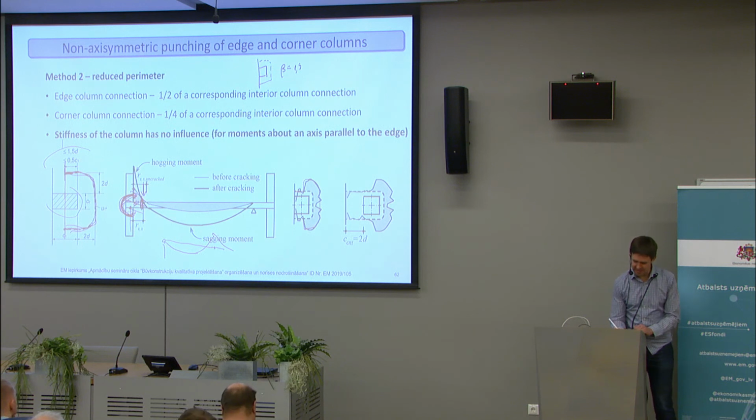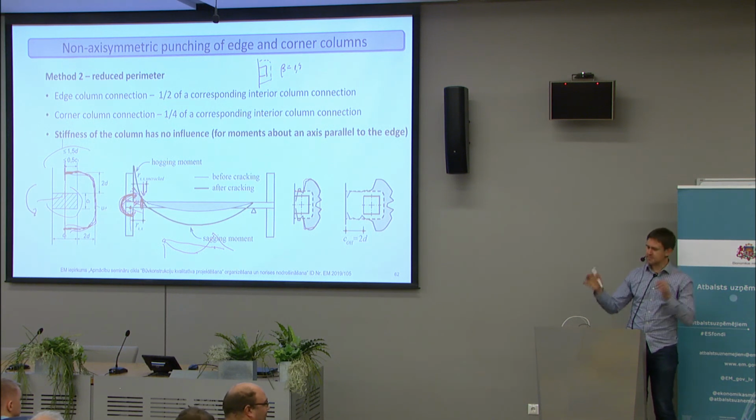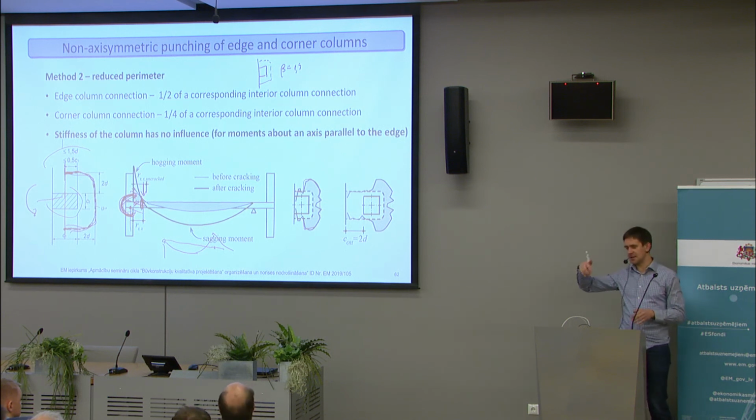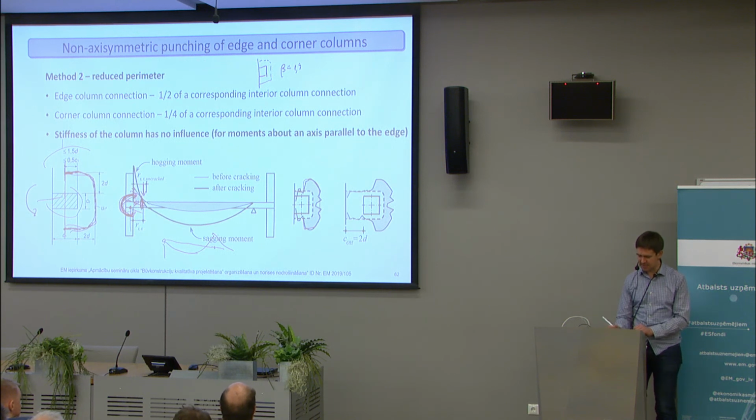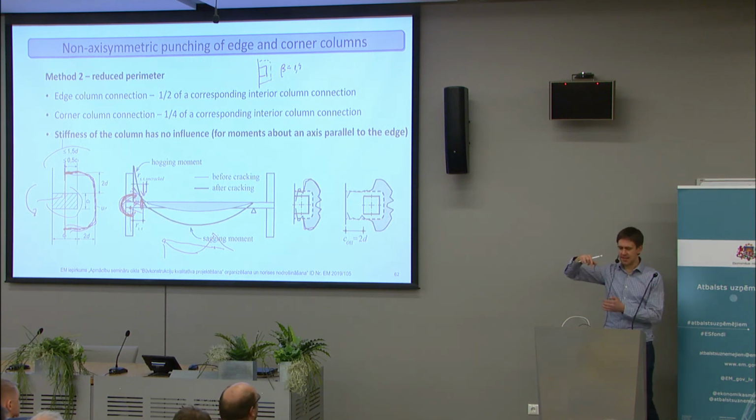If there is moment in the other direction, around the axis perpendicular to the edge of the slab, this is important. This should be considered, but the moment around the axis parallel to the edge, it's okay not to consider it.